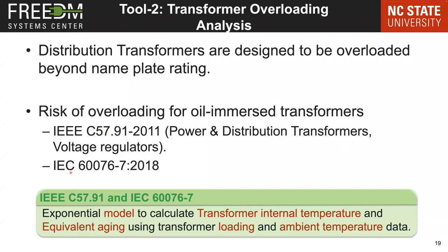an IEEE standard as well as a European standard. They both address the same issues, but using different mathematical models. So basically what we're going to use this standard for is the mathematical model developed here, which actually calculates the transformer internal temperature using the transformer loading and the ambient temperature profiles.